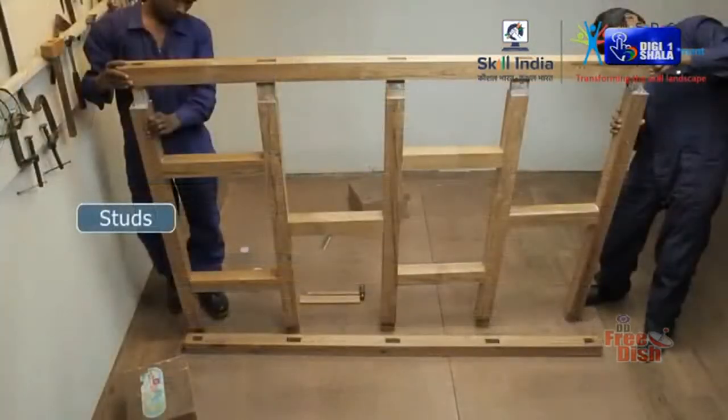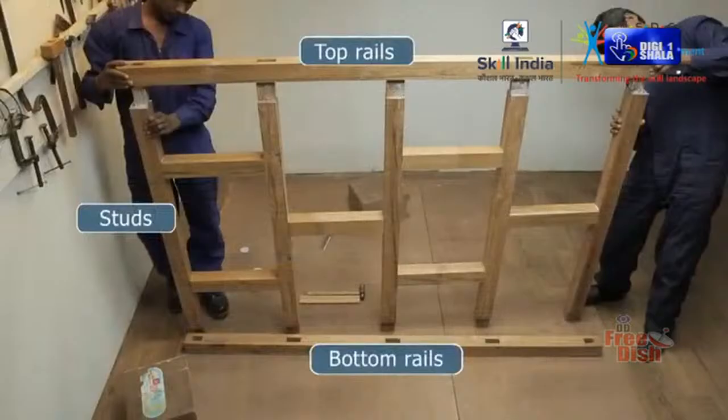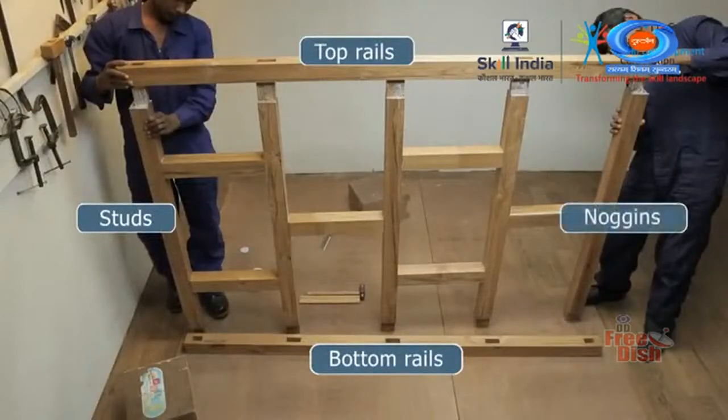The studs will fit on the top and bottom rails with a common mortise and tenon joint, and the noggins will be fitted to the studs with the stub mortise and tenon joint.